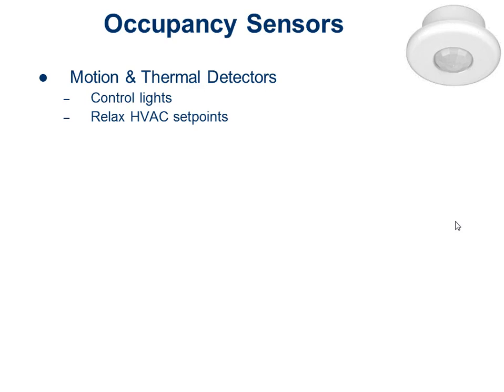So in the classroom example, when I said, hey, the kids are going to leave for an hour, leave the classroom, they're going to go to the library, okay, great. When they leave that room, this sensor basically sees there's no one moving in there, and 2 minutes later, it shuts off the lights. Maybe it relaxes the HVAC set points a couple degrees, and it shuts off the ventilation air. Then later on, when the kids walk back in there, see the movement, we turn it all back on. So that's good if you got spaces where it's go or no go. People are there or people are not there, like a classroom, for example.